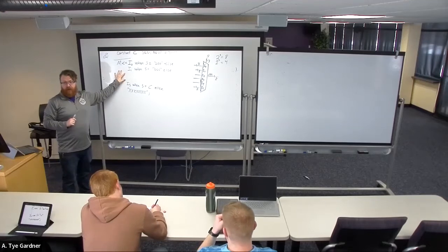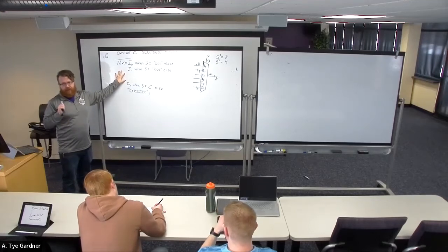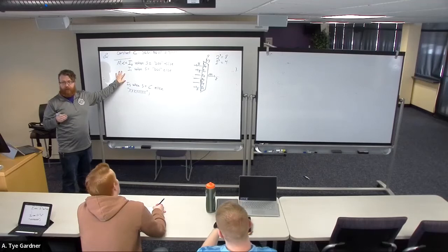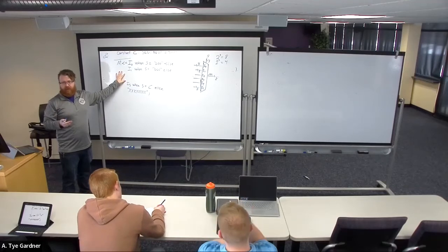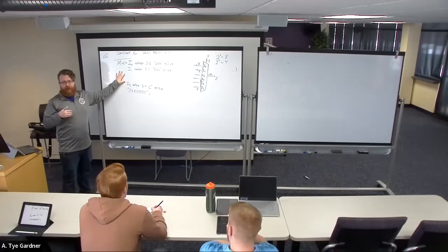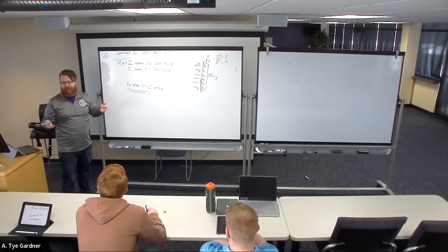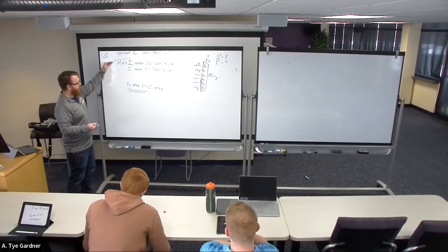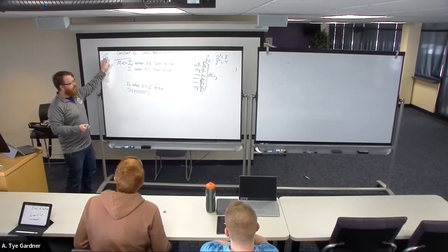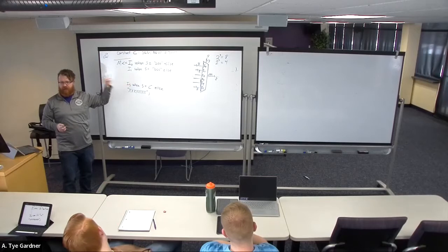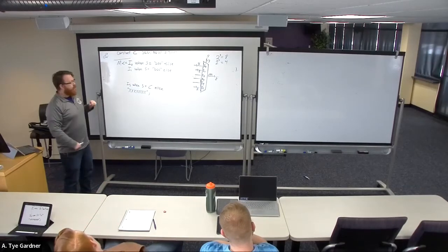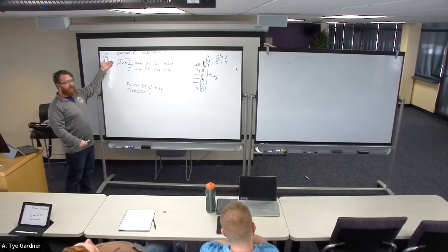Later, we'll design logic inside of a process, not just the test bench. That will be sequential logic that will depend both on the inputs and the previous outputs. It has memory, right? Sequential says this, then this, then this. This one is all of this happens at once. It's a mux, it's combinational. So this would be right after the architecture begins.